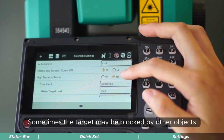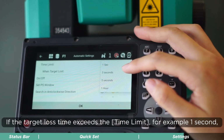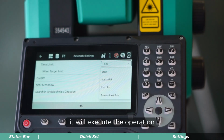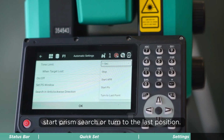Sometimes the target may be blocked by other objects. In this case, you can enable the prism prediction feature. If the target lost time exceeds the time limit, for example 1 second, it will execute the operation according to the when target lost option. It will stop motion, start auto prism recognition, start prism search, or turn to the last position.